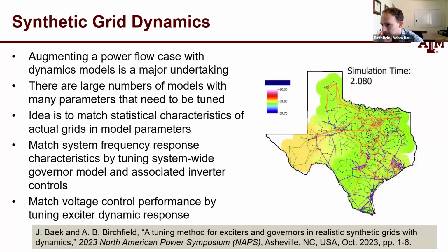Your response happens, and you can see the oscillations from one side of the network to the other. And then you can watch the grid stabilize to a certain frequency that's a little bit lower than the nominal value due to the droop control. So that is the synthetic dynamics. And of course, you can do this with a real grid as well, but it's just an example also of how various dynamics-related research could be demonstrated and used using these synthetic models.